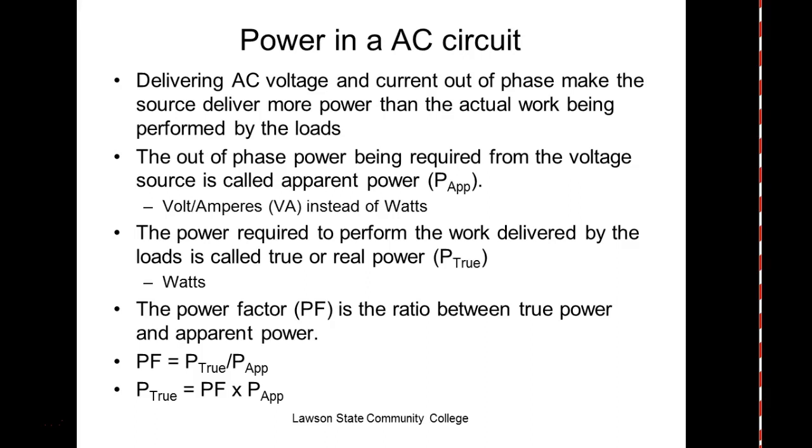So US Steel's got their own big capacitor banks out there on their substations that they switch in and out. And there's also a motor that can do it dynamically too. One of the things that can dynamically do it is a synchronous AC motor. So when I worked out there, Alabama Power had 2 synchronous AC motors that didn't need to be synchronous. They basically used them just for power factor correction. If you overexcite them, they'll want to lead. If you underexcite them, they lag. So they ran those all the time and monitored the power factor. If it got too low, they would just overexcite those synchronous motors and bring it back up.